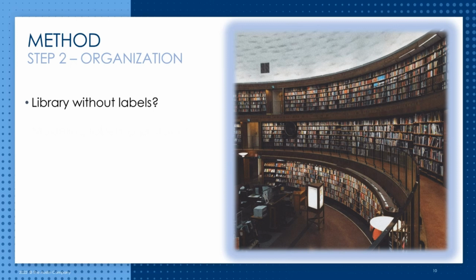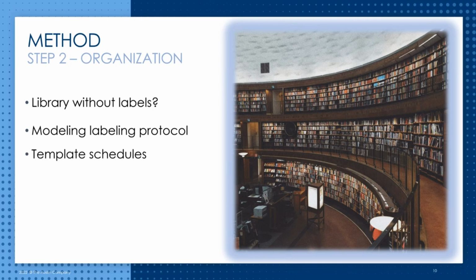So the team must establish a protocol of how elements are to be labeled. The organization and labeling process is followed in real time as the model is being developed to make easy retrieval of information possible later on. The BIM file organization scheme will also include setting up of schedules and views, which are ready to be populated with data as the model progresses.